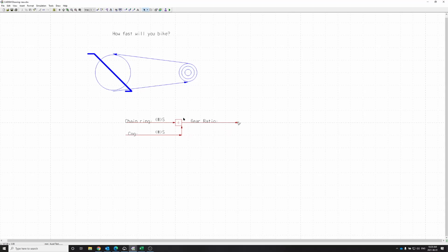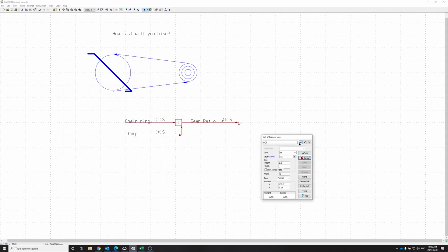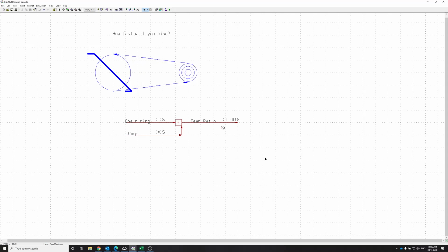Let's say OK. Let's also add a format on that guy, and we'll place it here. Now I am going to have some significant figures and decimal points. So to edit this, I can click the format, click this hashtag here, add a decimal and 2 more numbers, so I'll get more significant figures. When I click OK, it's going to ask me if I want to apply this to all my formats. I choose to just do it for the selected one.